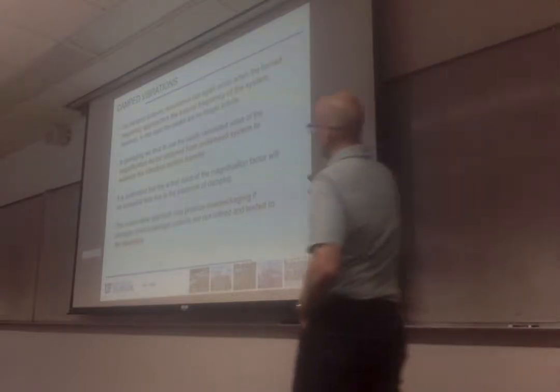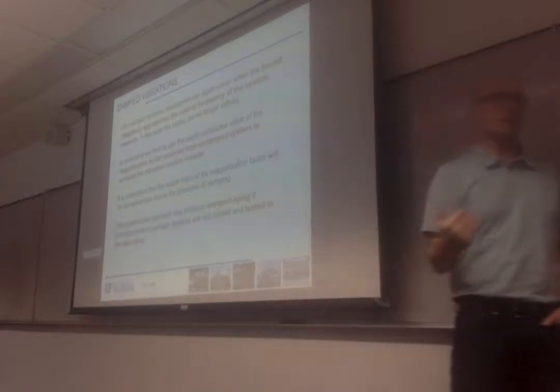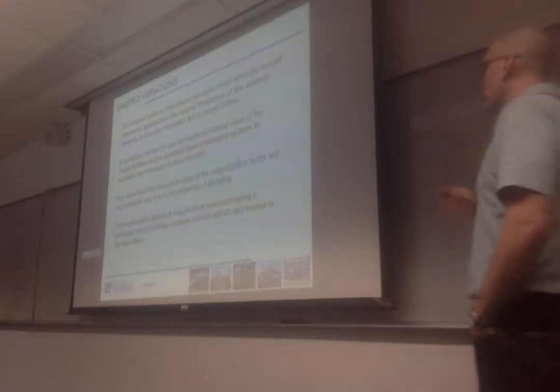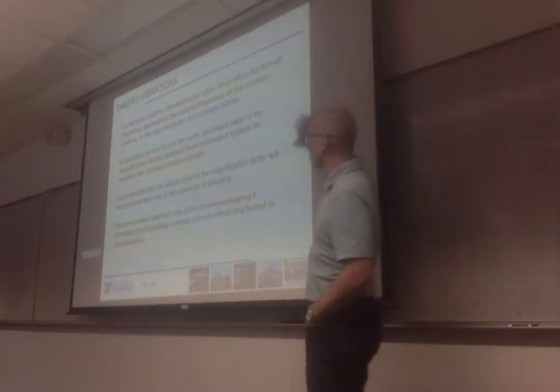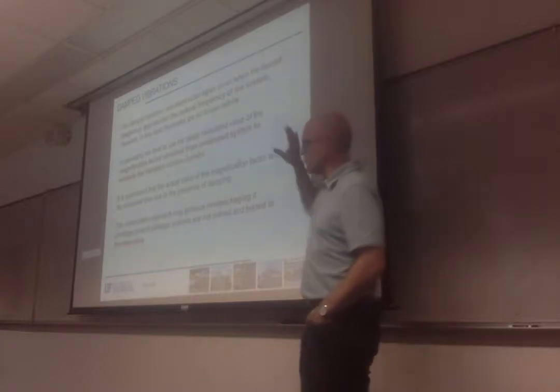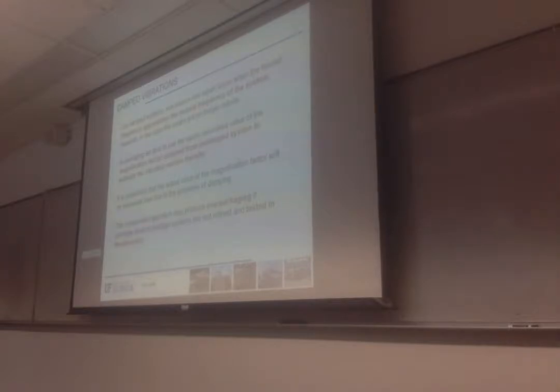It is understood, obviously, that the magnification factor will be somewhat less because of damping. And one thing we want to avoid, for sure, is over-packaging. If you use that approach we just discussed, it's kind of conservative. If you base your design only on this, you're probably going to get over-packaged.